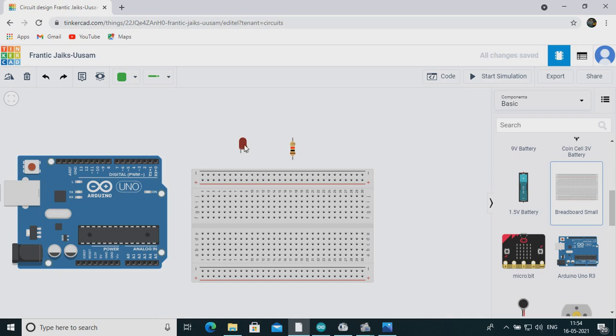Let's do the Arduino connections now. So first we need to put the LED here, right? These two ends we can see here: one is a little tilted one, and this one is a straight one. The tilted, curvy pin is the positive anode, and the straight one is the cathode, that means it's negative, getting? Just connect that, and this is a resistor.